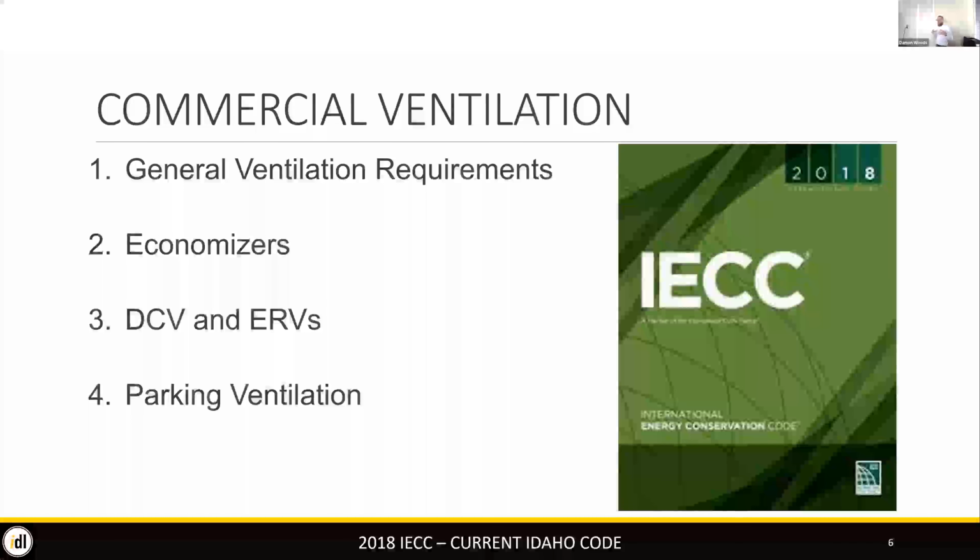But in terms of buildings, we're generally not dosed with 10,000 parts per million of CO2 in our faces. It's more about how do we keep enough fresh air in the space? Whether going above 1,000 parts per million, which is kind of the ASHRAE standard, really starts to impact performance or not is up for debate.